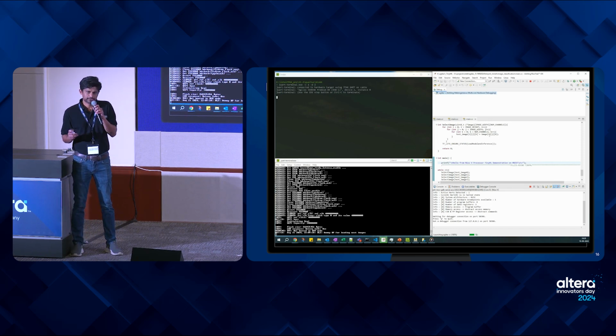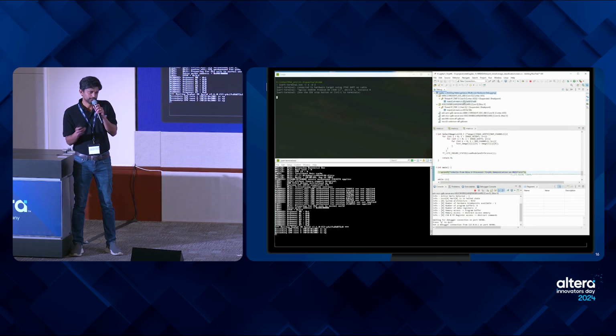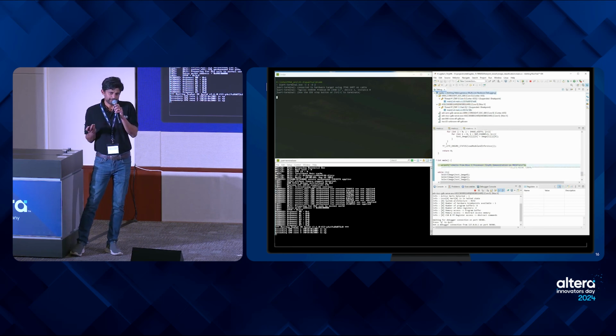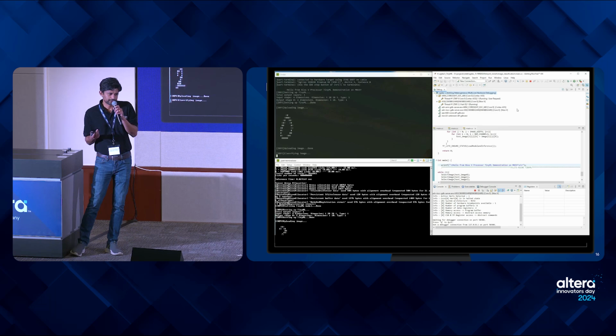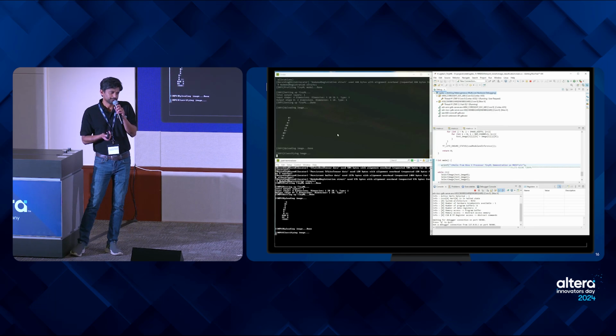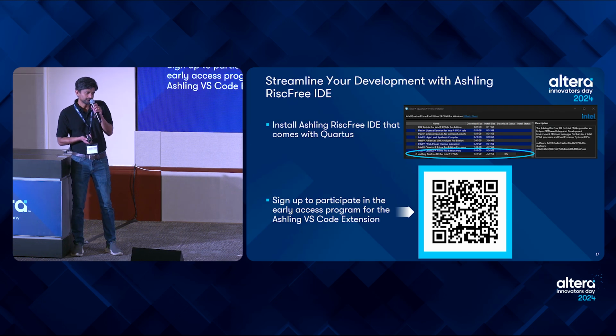And then once all the connections are made, you'll see all the call stacks, everything getting updated. And then we'll be in a situation to debug both the Nios V and ARM. So you can see now both the Nios V and ARM cores are listed there. It's all happening on an Agilex file system. And just free running on the target, you can see both of them running in parallel. So this is what we have for the demo setup there.